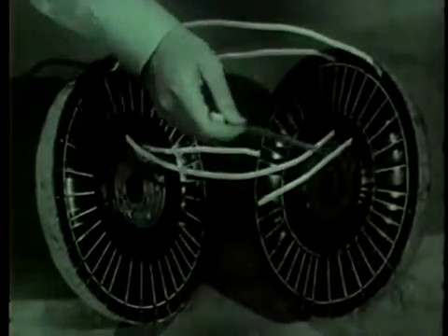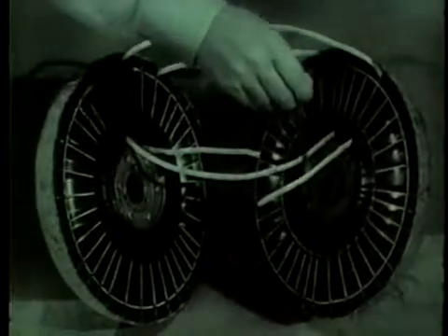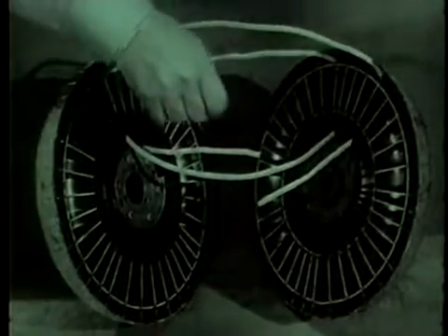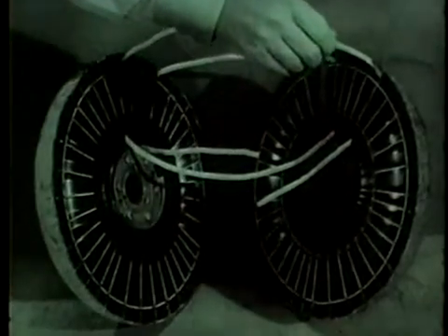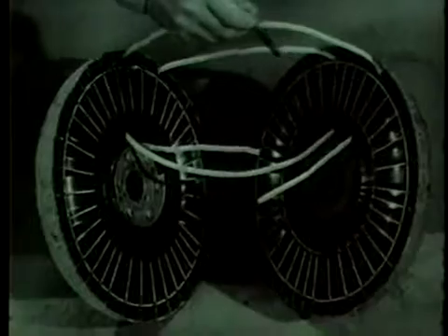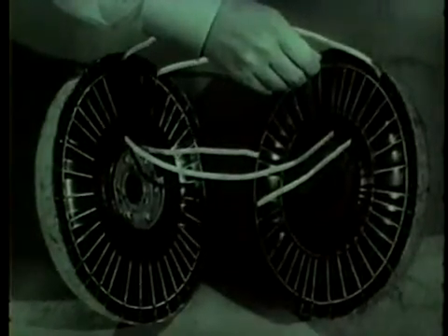This pipe cleaner, representing the oil in the fluid coupling, is now ready to show this motion, which is called the vortex motion of the oil within the fluid coupling. Because of the guide ring, uniform, non-turbulent vortex flow results, increasing the efficiency of the coupling.